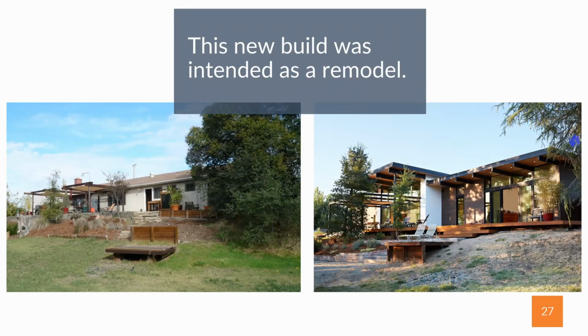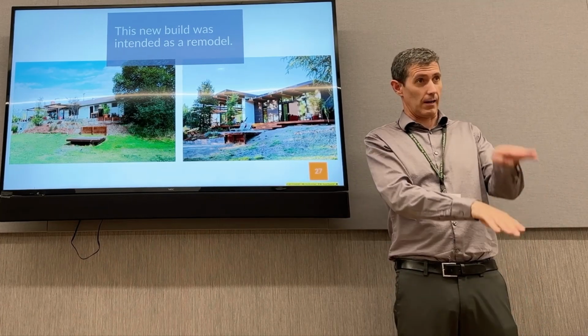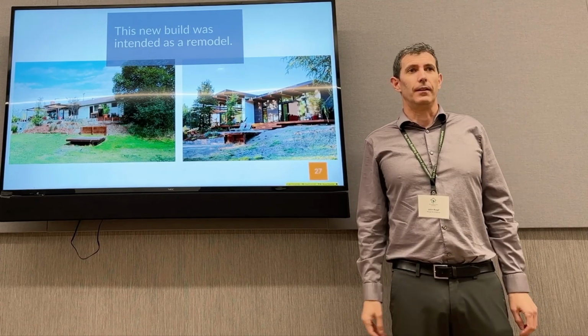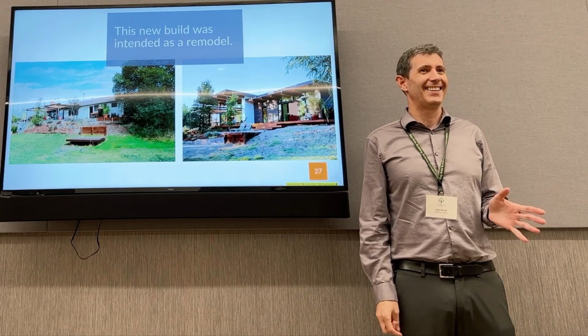So as examples, this home had a cracked slab right around there in this room, which I think was the dining room at the time. The slab was cracked, like offset. And I walked through it with the owners and I said, your slab is cracked, offset. You can't save that.